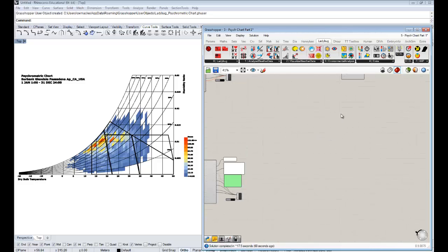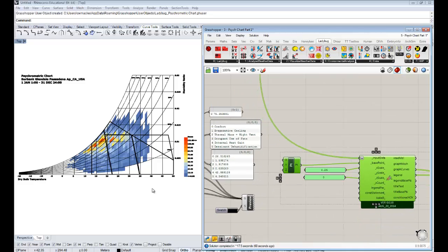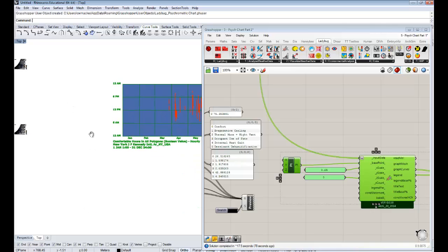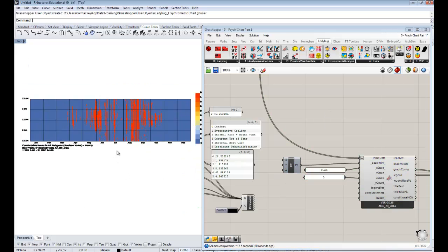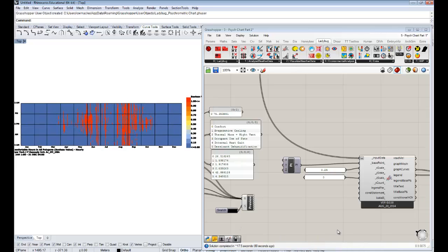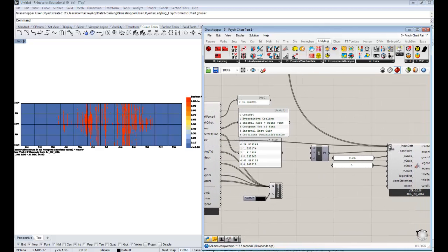So you see I still have the 3D chart from before, but I put some of my favorite parameters on it. And if you remember last time, this should still be in the Rhino scene, just far away. Yes. So we have the hours that were comfortable in New York, essentially, with just changing clothing, which weren't too many. But now we can take the strategy or not output here and plug that into this. And that's essentially going to make us a chart for each individual strategy that we just plotted on our Psych chart. So you can see the times of year when these things are relevant. I'm just going to fast forward because I know it's 5 charts and it's going to take a few seconds.